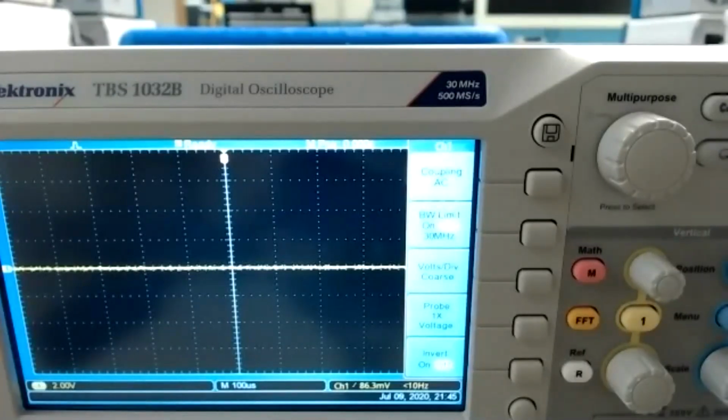And right now, we're gonna go over the steps. So I have my handout, and it says the initialization of the oscilloscope is required to set the instrument to a point from which all measurements can be referenced. The oscilloscope is going to be a reference. The following procedure should be used when the oscilloscope is used to quantify signals generated from transducers. Transducers could be sensors, could be instruments, whatever is providing a voltage output.